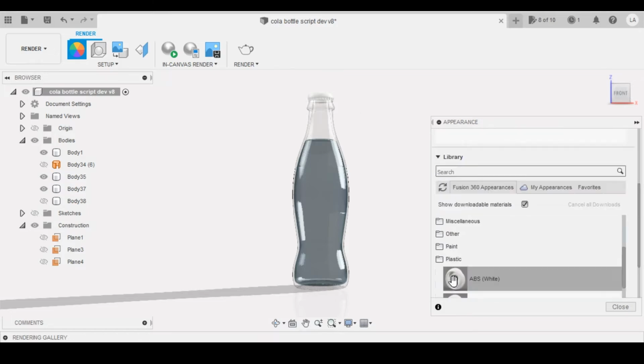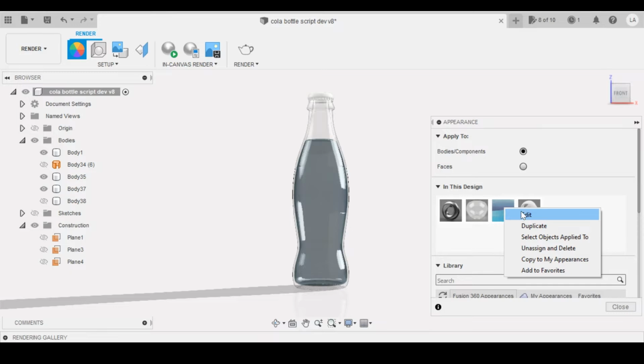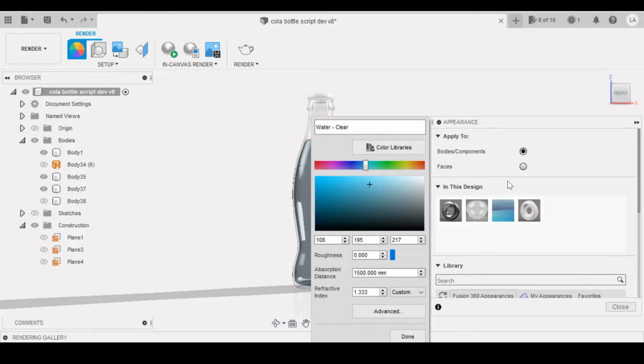and that's that. So to start with, we'll come up to water and we'll edit this material because we need to change the colour and a few other bits on it. So firstly, the colour, we'll change these figures here to 40, 6 and 0, which gives that bit of a darker browny reddy colour, which is kind of similar to what Coca-Cola is.